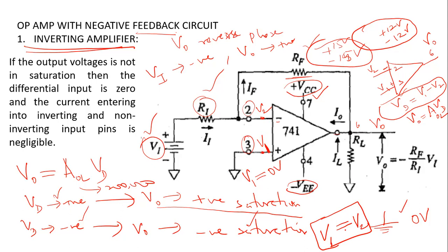Now, that is all because of this feedback circuit. As you can see, it is supposed to drive into either positive saturation or negative saturation, or flip between them, but this actual op-amp, when it is in operation, has a very interesting property that it will set these two voltages V1 and V2 to be equal. So instead of flipping between positive and negative saturation, it sets V1 equal to V2 almost spontaneously.